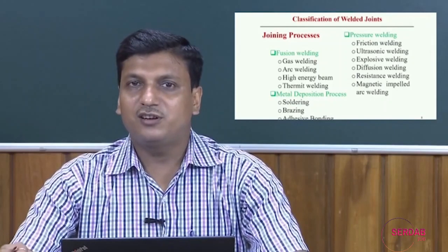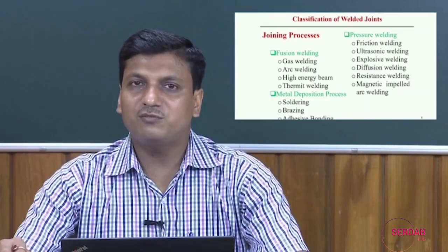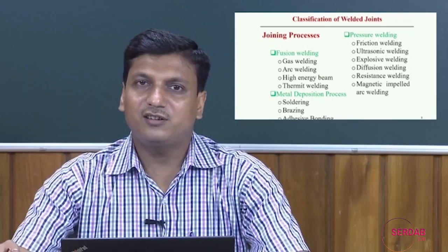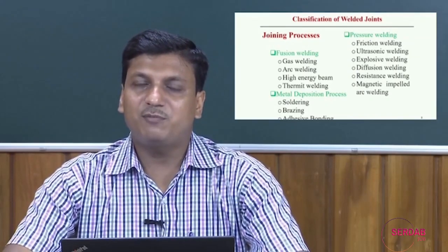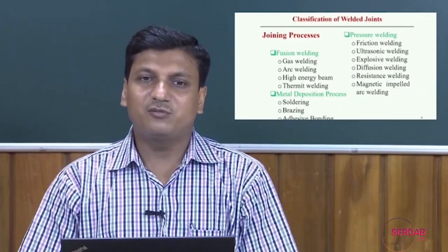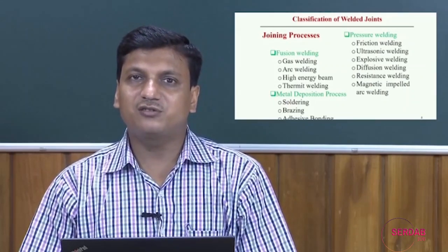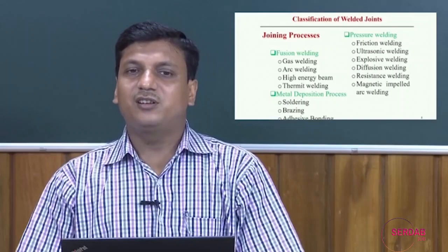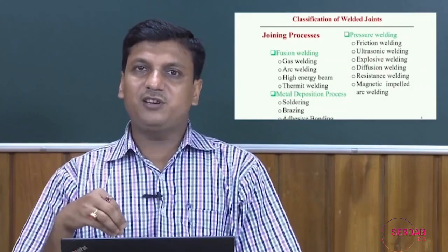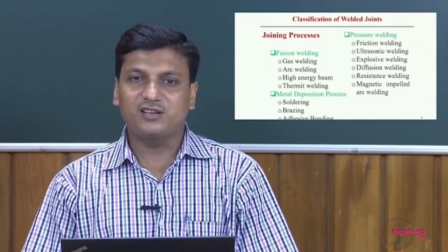In explosive welding, using some explosive, the components are highly deformed. A high rate of plastic deformation happens within the component, and then these two components can join in the solid state, creating a solid state welding process. Similarly, in resistance welding we apply resistive heat, but at the same time to make the joint we need to apply some mechanical load as well.